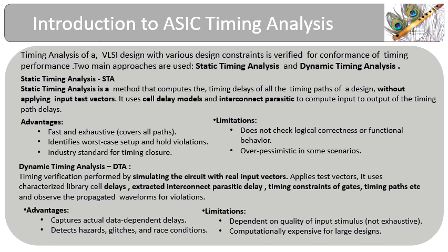Dynamic timing analysis, or DTA, simulates real input vectors through the circuit. It captures actual data-dependent delays and detects glitches and hazards. DTA offers deeper insight into timing behavior but at a high computational cost. Large designs make exhaustive simulation impractical and expensive.